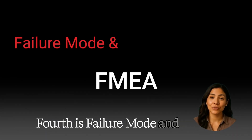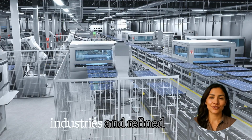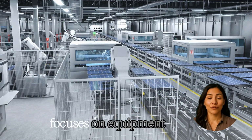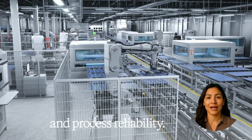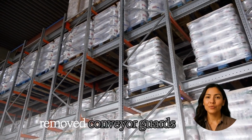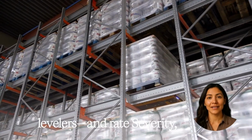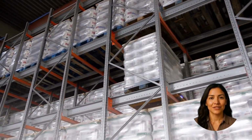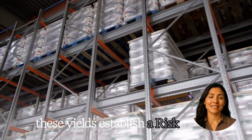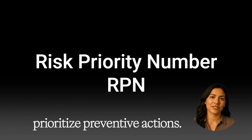Fourth is failure modes and effects analysis, FMEA. Born in high-reliability industries and refined in automotive, it focuses on equipment and process reliability. Teams identify failure modes, for example, removed conveyor guards or malfunctioning dock levelers, and rate severity, occurrence, and detection. Traditionally, multiplying these establishes a risk priority number, RPN, to prioritize preventive actions.